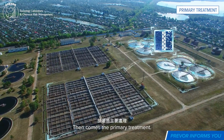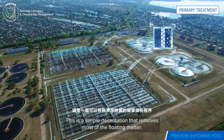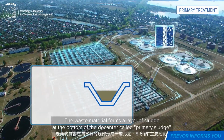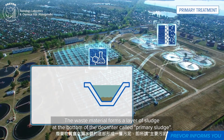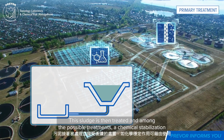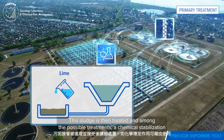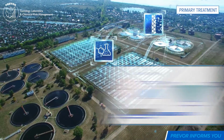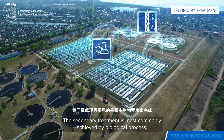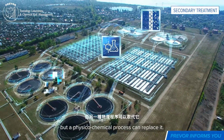Then comes the primary treatment. This is a simple decantation that removes most of the floating matter. The waste material forms a layer of sludge at the bottom of the decanter, called primary sludge. This sludge is then treated, and among the possible treatments, a chemical stabilization can be carried out by using lime, a corrosive product.